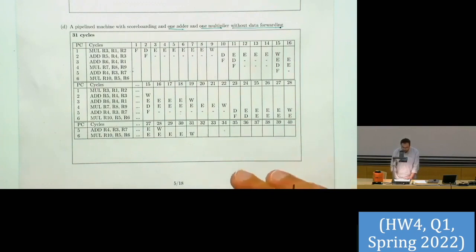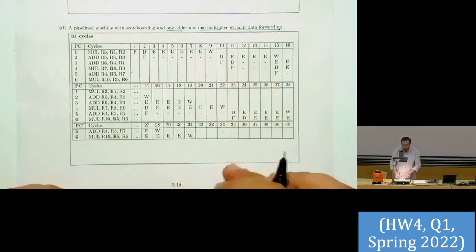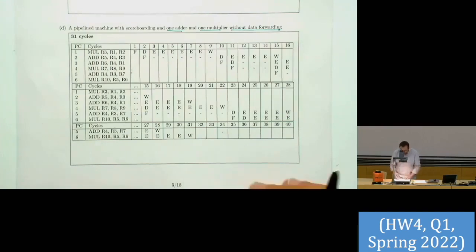We assume that once we start using an adder for an instruction, we cannot pipeline inside this adder. We just give the inputs to this adder, and we get the output at the end of the 4th cycle, or in the multiplier case, at the end of the 6th cycle.